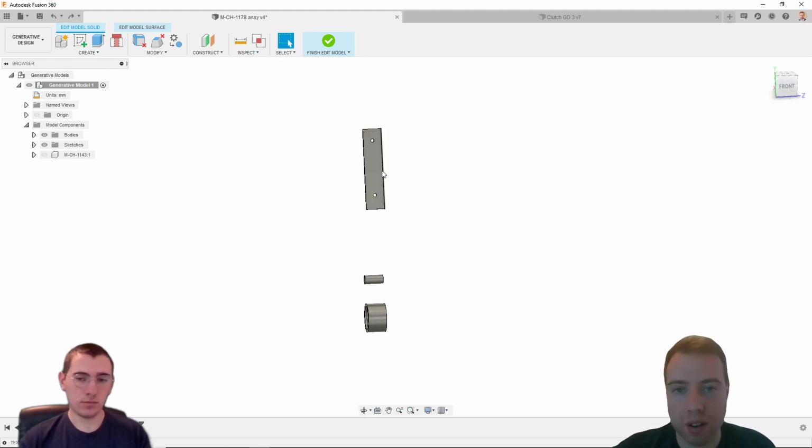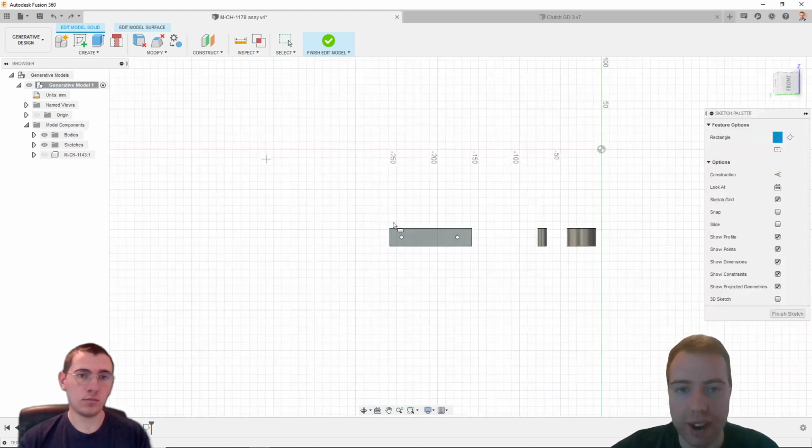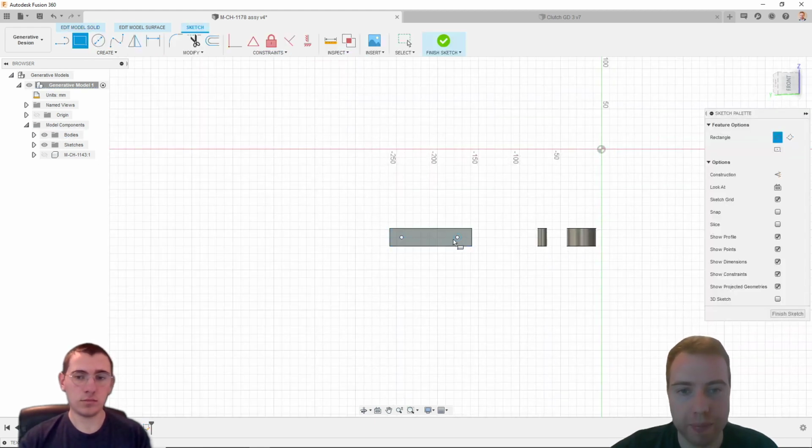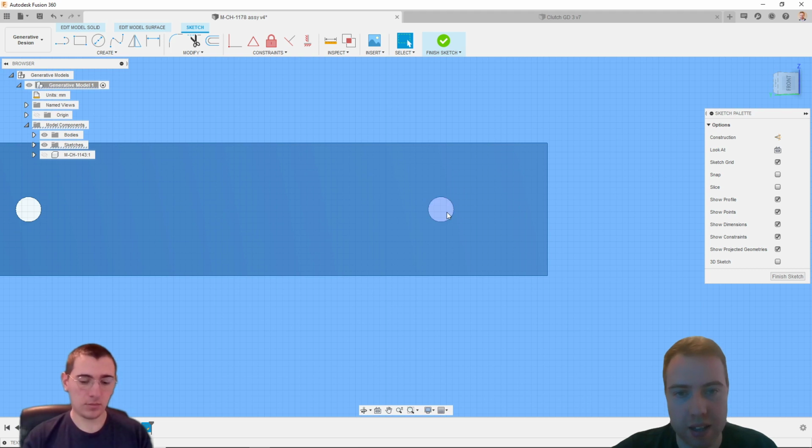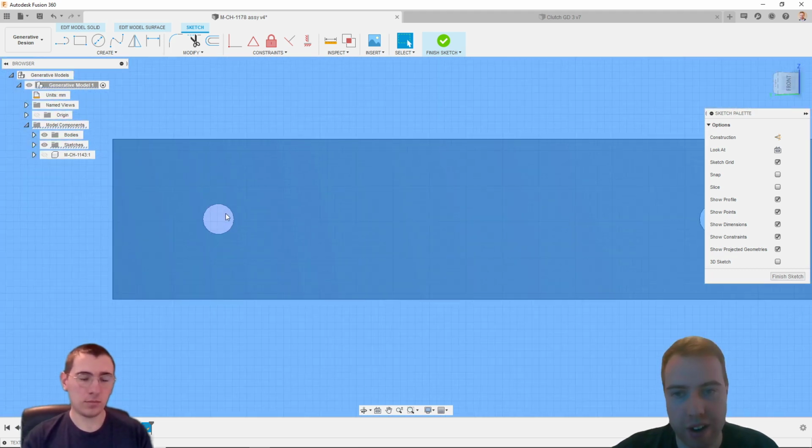We spoke about the first one, which is that I need to make sure that we have space to push the clutch pedal with my foot. What I'm going to do again is just create a sketch on this plane here, and create a kind of surface basically. I'm just going to select every element of that profile.